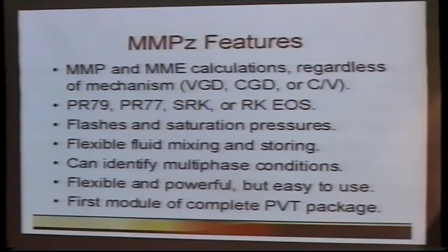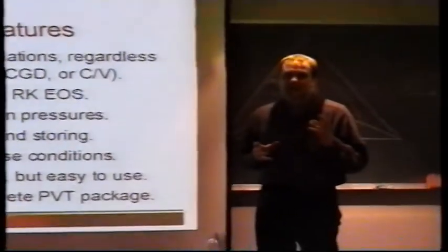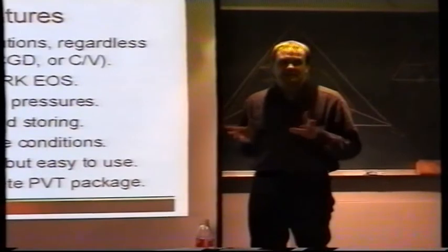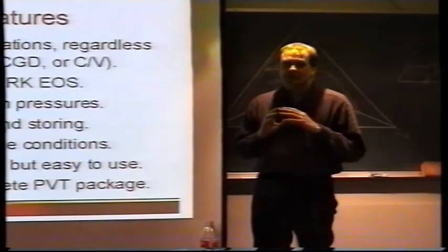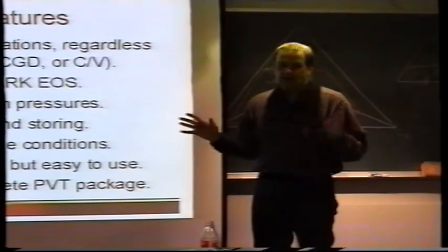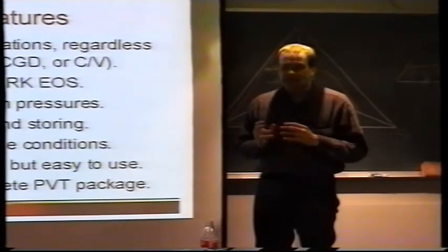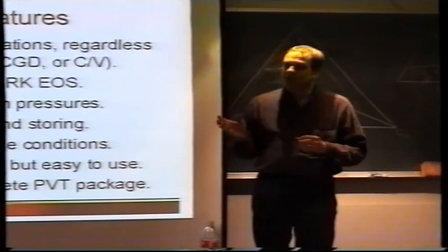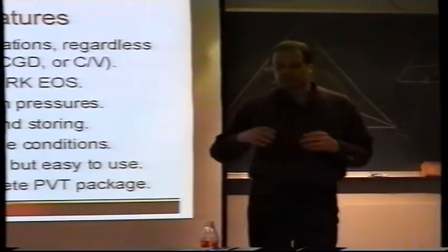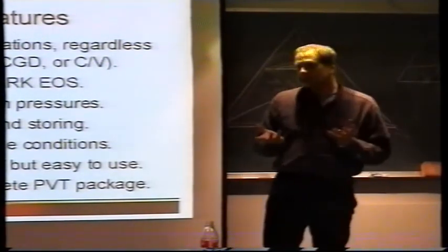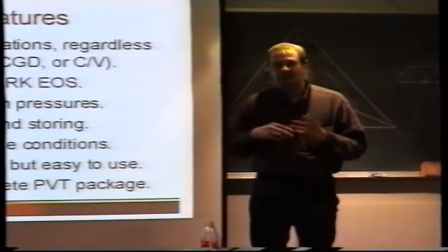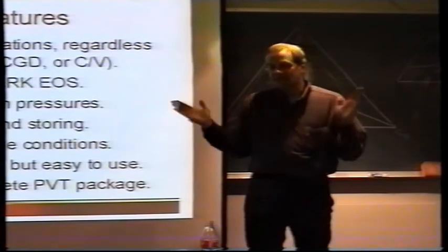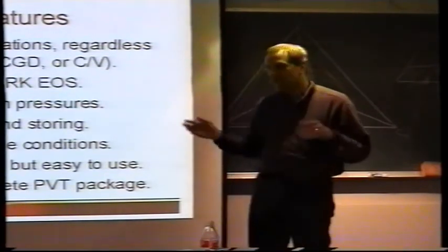But if you have an EOS model that predicts a 3-phase region, and you try to run reservoir simulations with that model, the simulator is going to just crater. It will not be able to get through those 3-phase calculations, because it's only calculating a 2-phase solution, and it'll oscillate between 2 different choices until the time step goes to 0 and the simulator gives up.